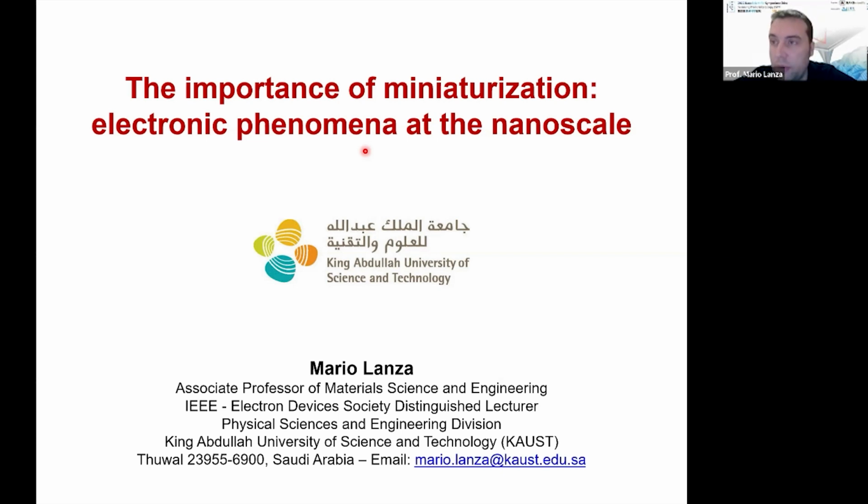And then tune your recipe. If you are fabricating, for example, memristors, you may need to adjust this. If you are fabricating transistors, maybe you need to tune the number of defects in the channel, and you may tune the electrical resistance. There are papers that say that depending on the material of the electrode, depending on the geometry of the electrode, you can reduce it.